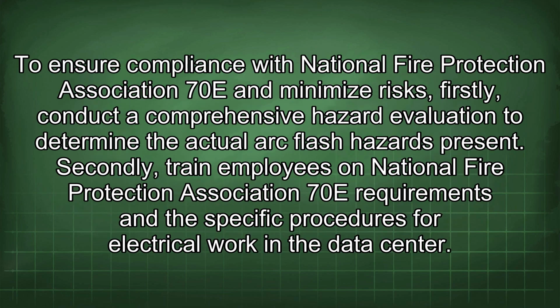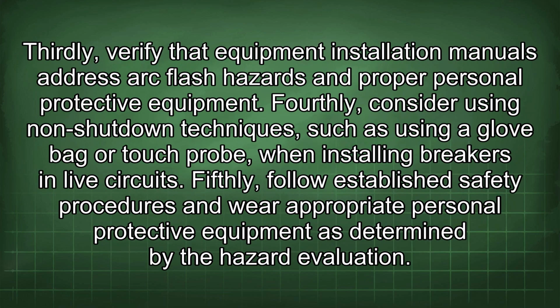To ensure compliance with National Fire Protection Association 70E and minimize risks, firstly, conduct a comprehensive hazard evaluation to determine the actual arc flash hazards present. Secondly, train employees on National Fire Protection Association 70E requirements and the specific procedures for electrical work in the data center. Thirdly, verify that equipment installation manuals address arc flash hazards and proper personal protective equipment.